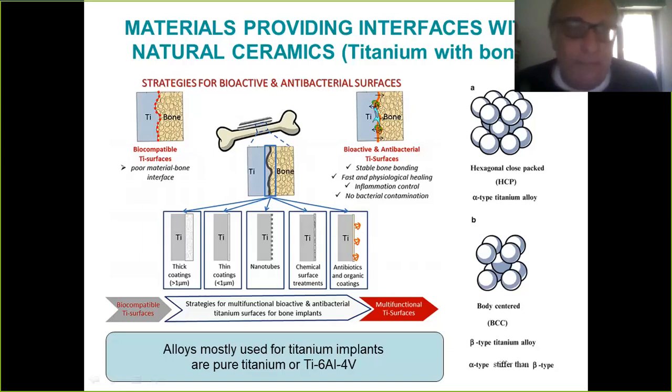They might not be bio. Titanium is not bio at all, but it is a metal which is produced by industrial methods. But it is biocompatible, then it is a biomaterial. It is a huge field. There are a number of journals dedicated just to biomaterials, but one of the alloys which works particularly well is titanium with 6% of aluminum and 4% of vanadium.